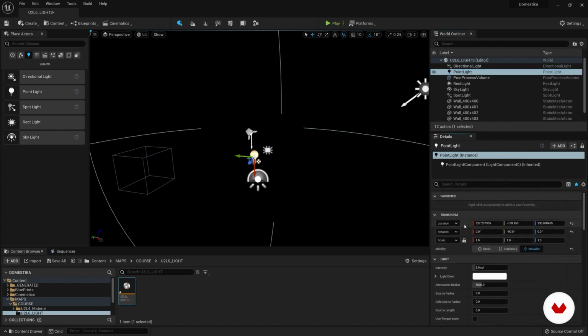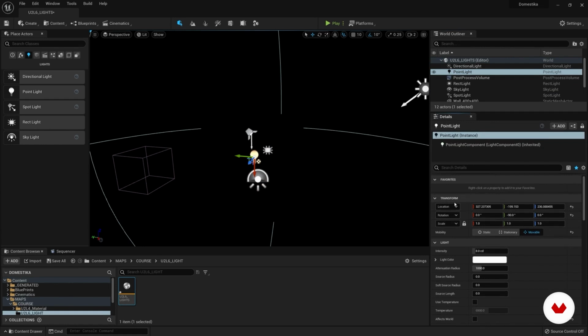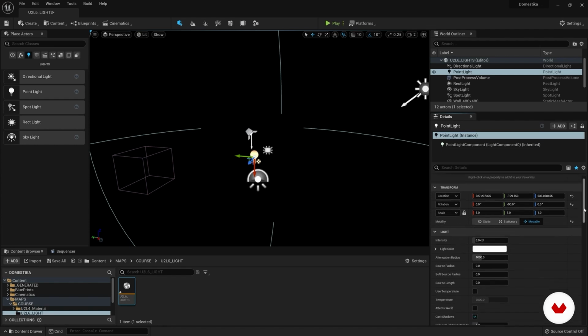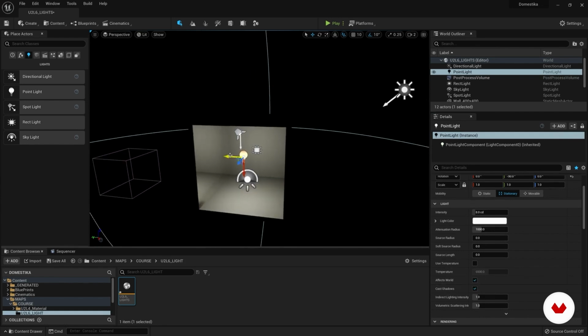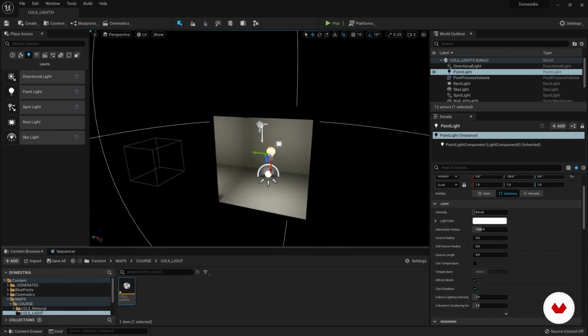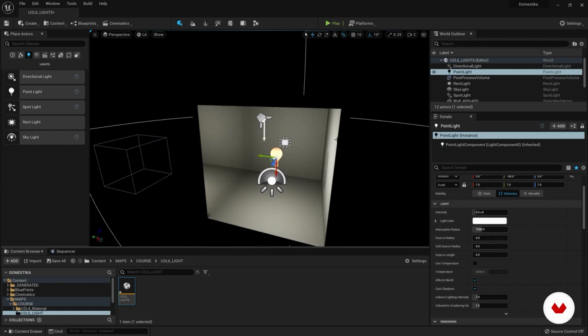We note that, like all objects staged on Unreal, in the Details tab we have the Transform section with location, rotation and scale. But here is this new option, which is mobility. The first two, static and stationary, relate to video game development. They make the lights non-dynamic, in the sense that with the rendering procedure, these lights are then, in jargon, cooked, and their influence on various objects is inscribed in other textures and printed.